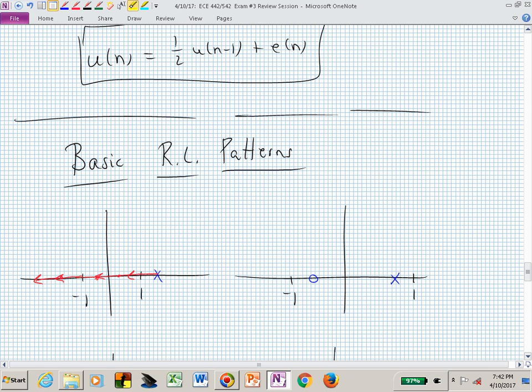If I ask that, now you're thinking about this and you're saying, oh, does K equal 0 stabilize that system? No, I have to crank up the gain to at least get me to this minimum value of K, which is the K expression, the K formula, evaluated at z equal to 1.